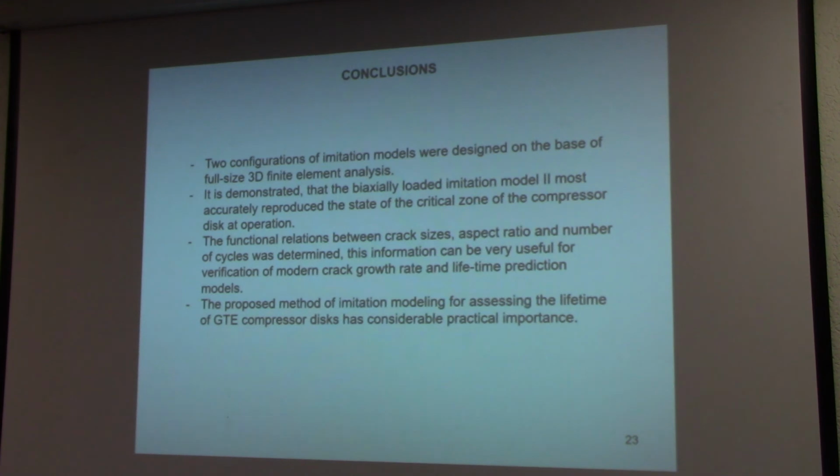And conclusions of my work. Two configurations of imitation models were designed on the basis of full-scale finite element analysis. It is demonstrated that the biaxially loaded imitation model number 2 most accurately reproduces the state of the critical zones of the compressor disk at operation. The functional relations between crack sizes, aspect ratio, and number of cycles were determined. The proposed method of imitation modeling for assessing the lifetime of GTE compressor disks has considerable practical importance.